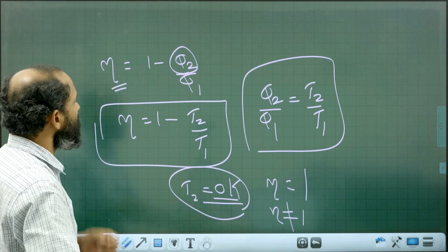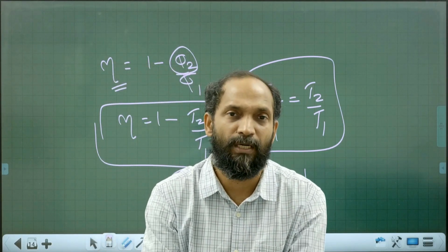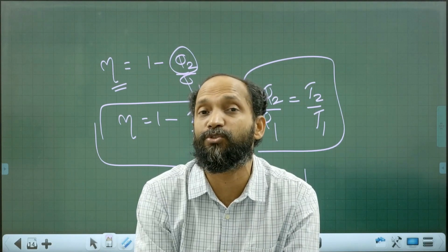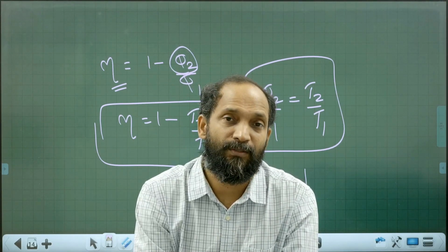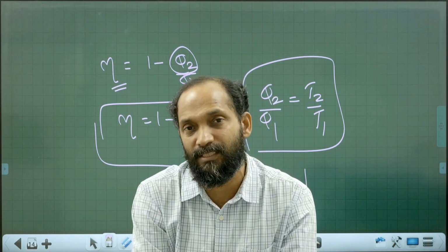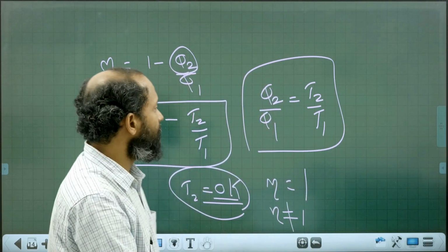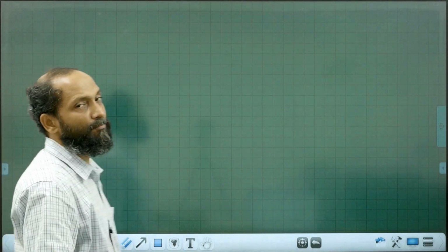Okay, Carnot engine is an ideal reversible heat engine which works on two temperatures T1 and T2. The working substance of Carnot engine should be ideal gas. No engine can be more efficient than Carnot engine whose operating temperatures are T1 and T2, where T1 is greater than T2. Now, the thermal capacity of the source and sink must be much larger, so that any amount of heat added or removed will not change the temperature of that source and sink.